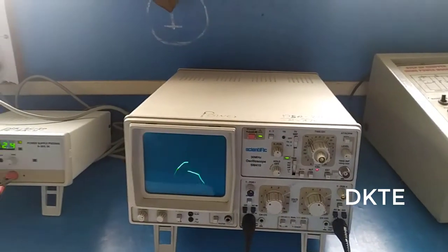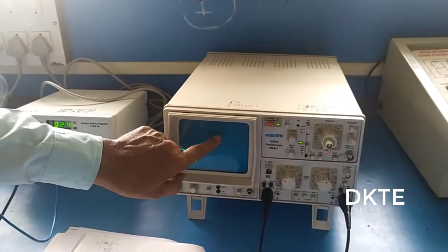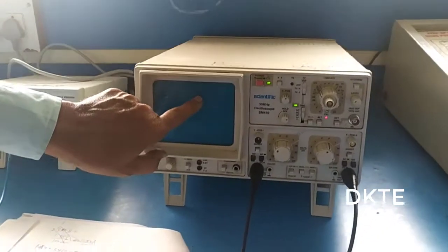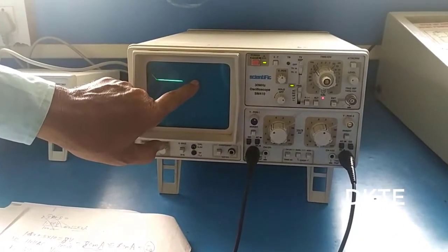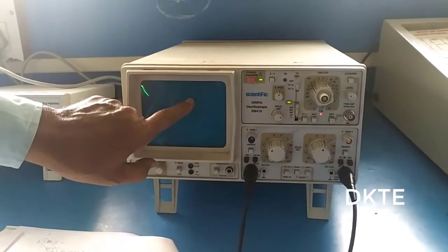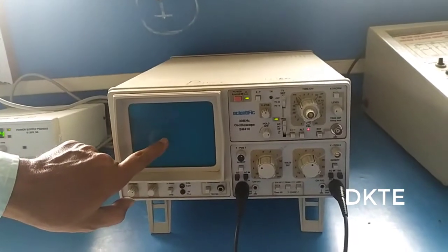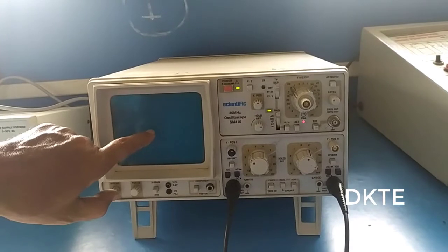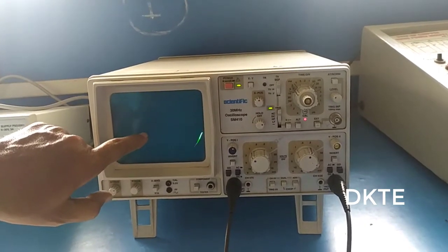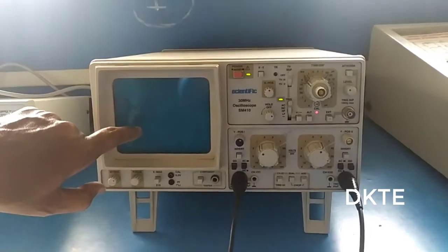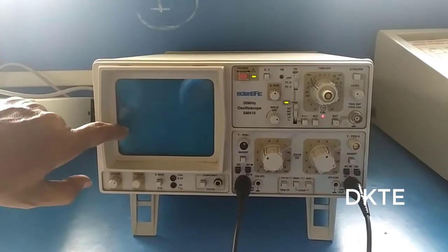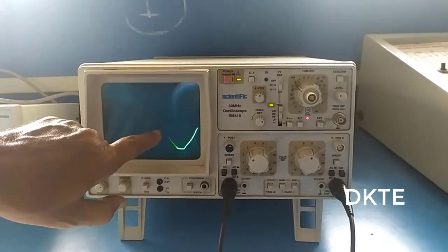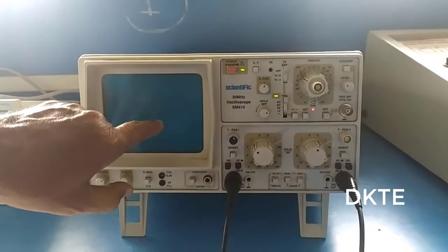This is for this particular state of the Vg. This is the alpha non-conduction state of the SCR. Here conduction takes place, and this is beta, and here the non-conduction takes place from the zero crossover point, negative cycle, and this is alpha. Alpha plus negative half cycle pi is the non-conduction state of this SCR, and this is the conduction state of this SCR. This is the beta.